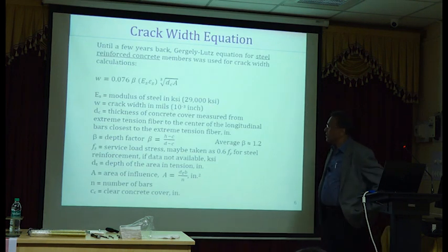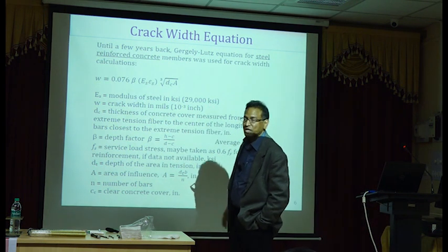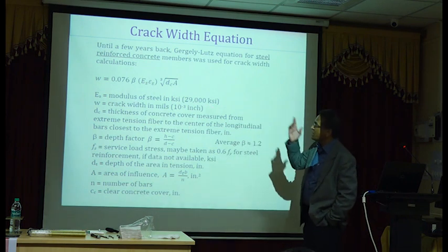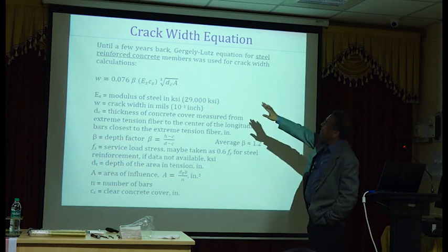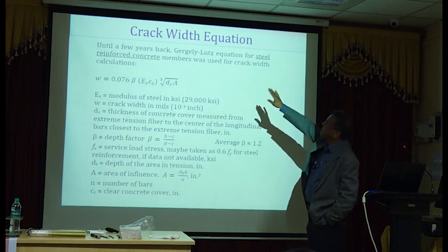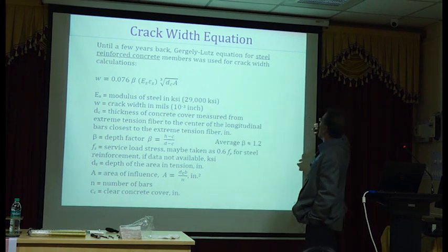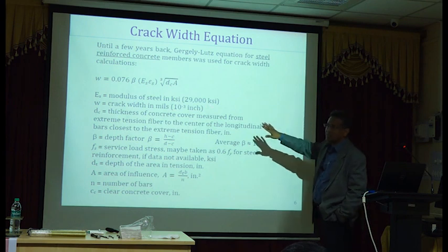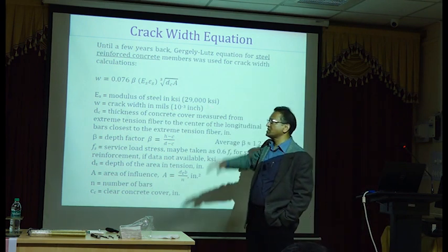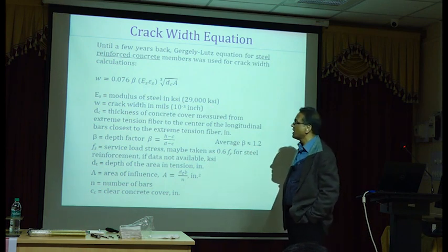Those of you who are familiar with crack width equations, IS 456 is actually based on this equation. The original equation was suggested by Gergely and Lutz. This Gergely equation is very famous. It was developed in the 1960s or something like that. Nobody has changed that until this point.